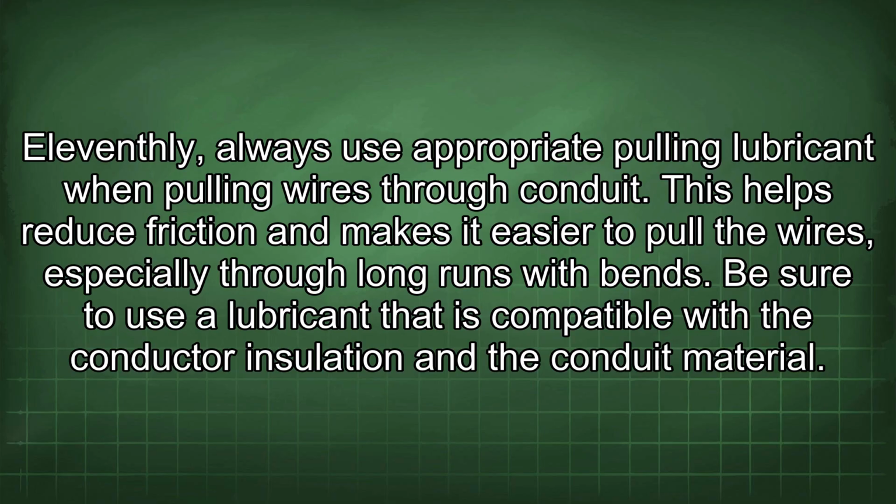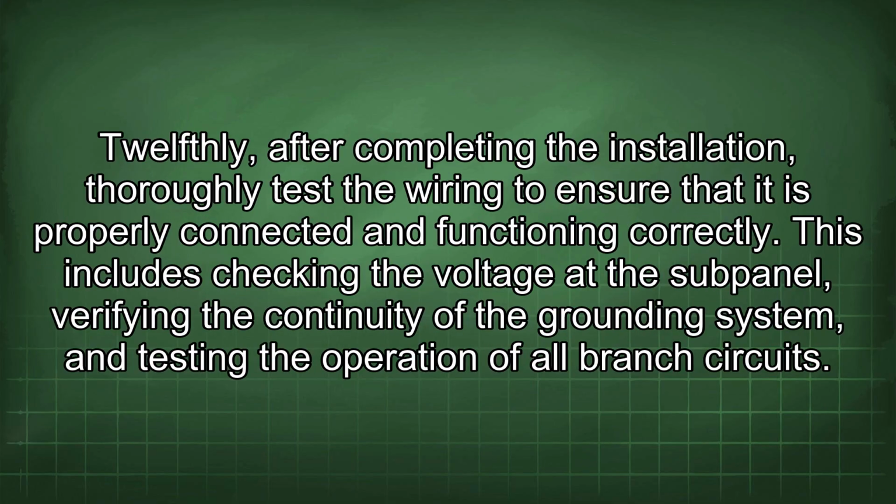This helps reduce friction and makes it easier to pull the wires, especially through long runs with bends. Be sure to use a lubricant that is compatible with the conductor insulation and the conduit material. 12thly, after completing the installation, thoroughly test the wiring to ensure that it is properly connected and functioning correctly.